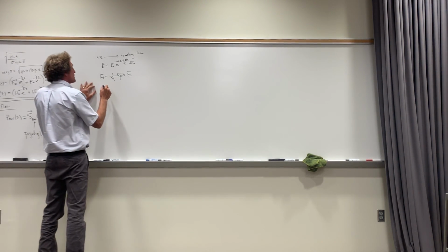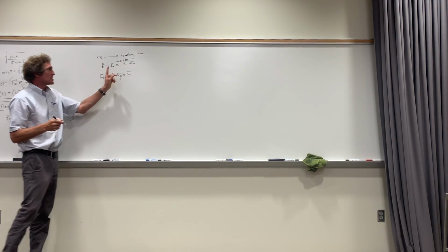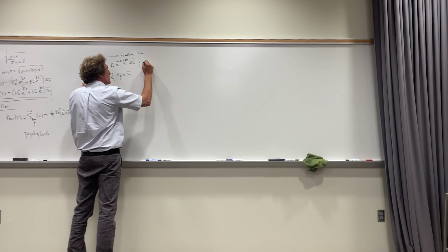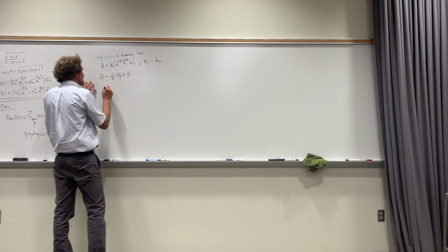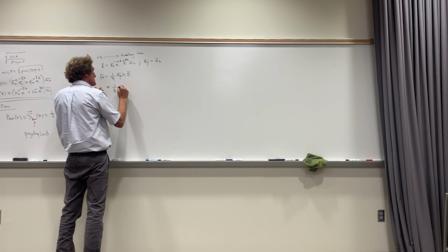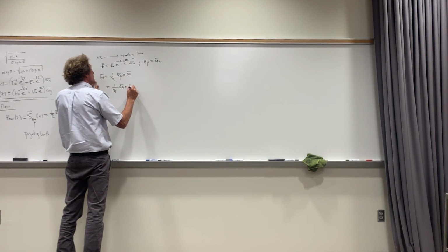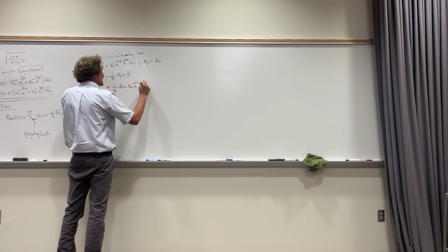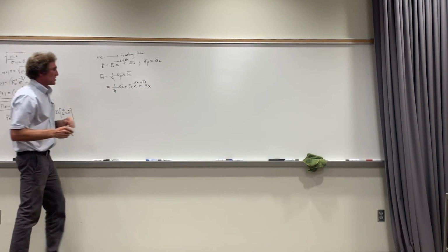So for this, the H field would be equal to, by the way, what is the direction of propagation for this wave? Z direction, positive z direction, so you can just say that the unit vector in the direction of propagation is simply az. So this is going to be 1 over the impedance, and it's going to be times az crossed into the E field. Well, the E field has got E naught, and it's got e to the minus gamma z, and it's e to the minus j beta z in the ax direction. That's an x. Do y'all agree with me, class?